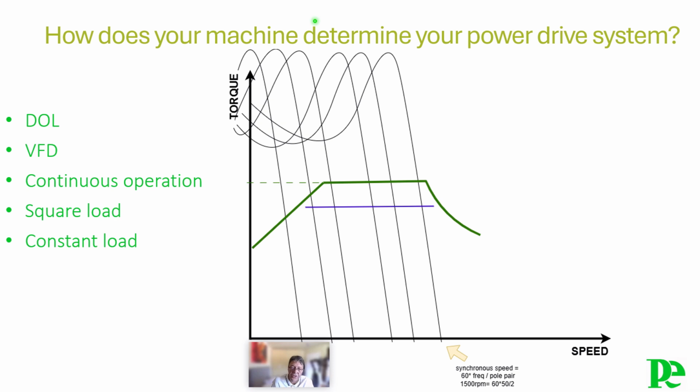Examples for constant torque include conveyors, augers, reciprocating compressors, crushers, positive displacement pumps and kilns. Continuous operation above the declining green line and up to the dotted green line is only possible in case of forced cooling, for example totally enclosed fan cooled or IC416.